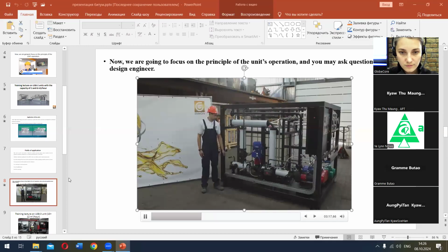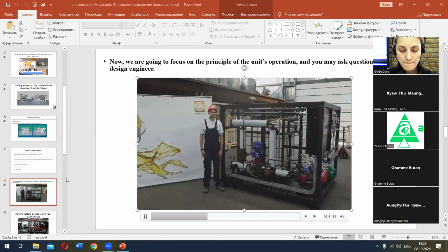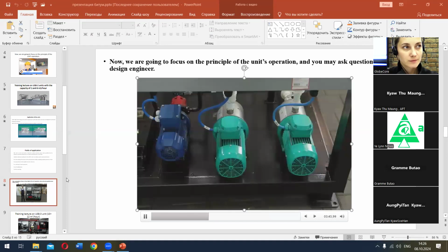In order to prepare the unit for operation, thermal oil is supplied to the components of the bitumen emulsion section, thereby heating them to the temperature of 110 degrees Celsius. Furthermore, the bitumen is concurrently heated outside the unit to a temperature of 140, 160 degrees Celsius, and the water is concurrently heated outside the unit to a temperature of 40, 60 degrees Celsius, and both are fed into the unit.